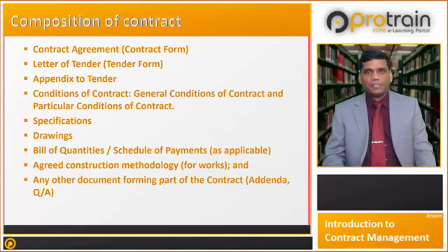Specifications provide the information about the scope of works, general and technical requirements of the contract. They also provide information about material standards, details of the samples to be provided, and tests to be carried out. The method of executing the works is also included in the specifications. Provisions of access or space for other contractors are also part of the specifications.